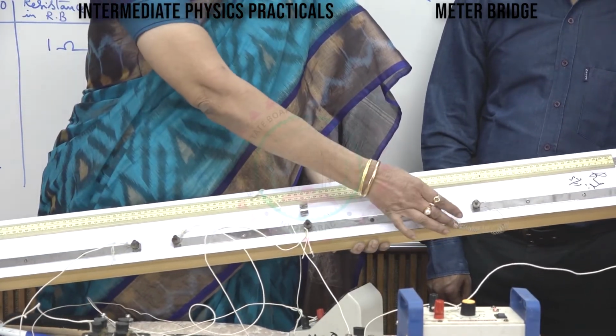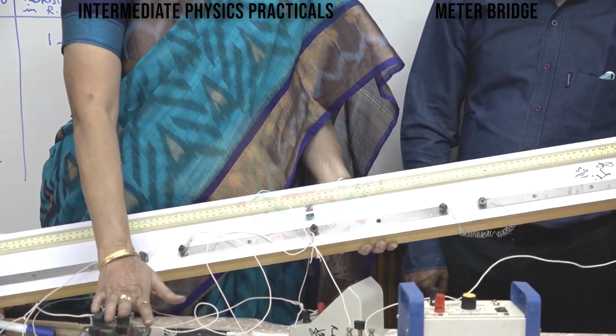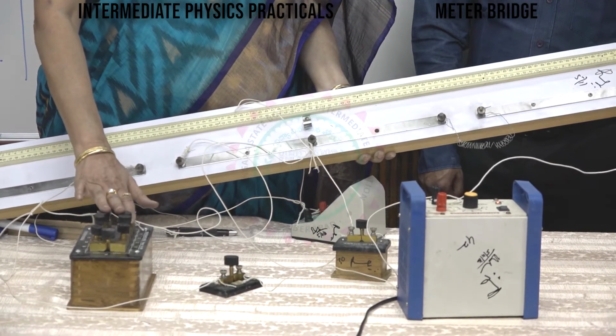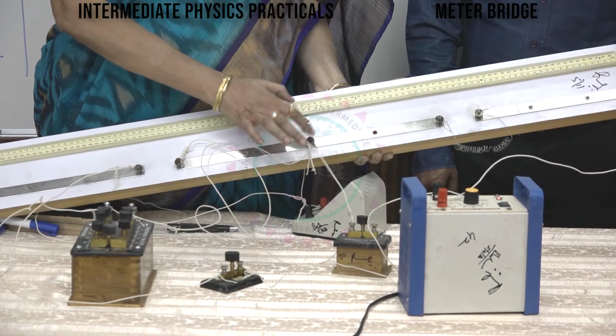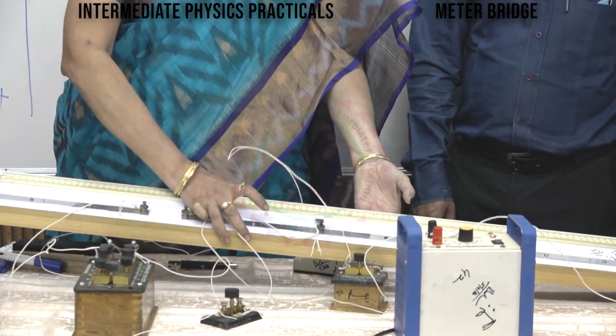Now this is the unknown resistance X we are calling, and known resistance which you are applying from the resistance box is connected here. Now what we are going to connect from the midpoint, from this binding screw, I shall explain soon. So that is about meter bridge.